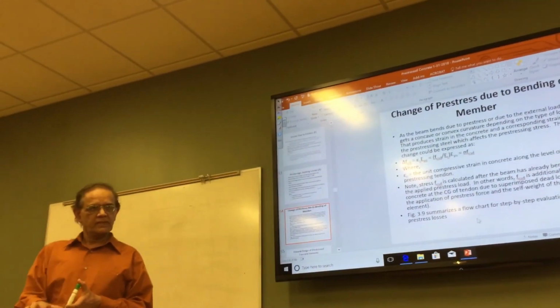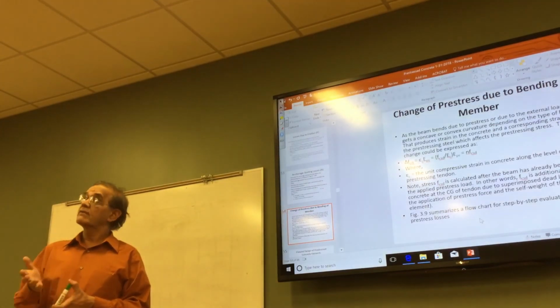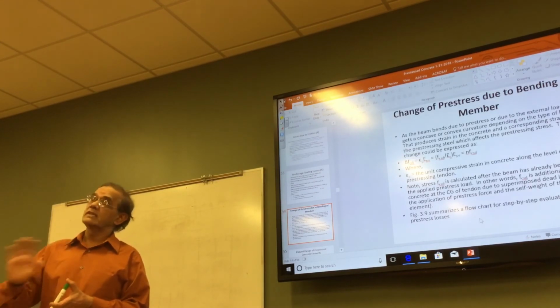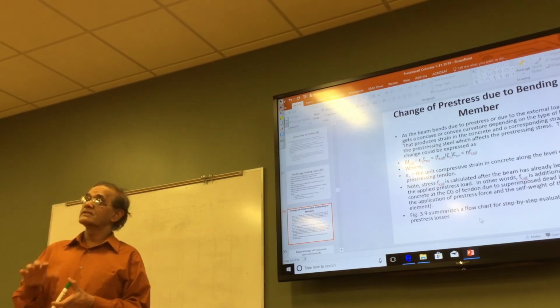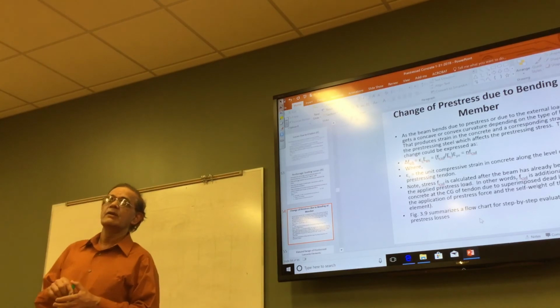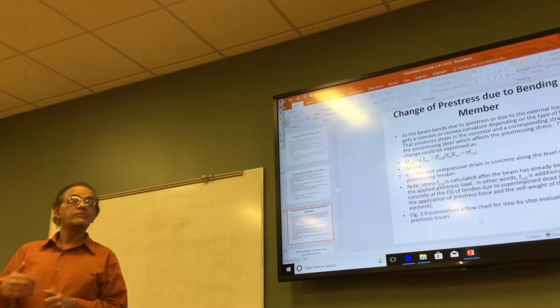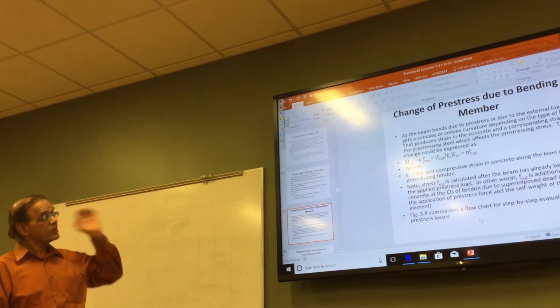So if you have a settlement, then the settlement is immediate if it is a sandy or gravelly soil, right? If it is the clay soil, especially expansive clay, then it is a different behavior. Now, we are not teaching or discussing geotech here, but our material is like that. Our material behaves like clay or wood, time dependent, sustained versus non-sustained loads. So that's why we need to check.